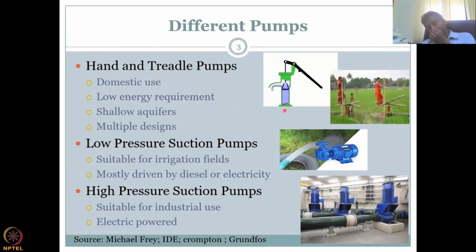So here you have the pump base and the cylinder, where the cylinder has water, and the water is pulled up when you push the piston down, the piston or the handle, and that opens these valves. You can see the valve opening, and this valve in the pump handle opening, and so it brings up the water and releases it through the mouth or output valve.